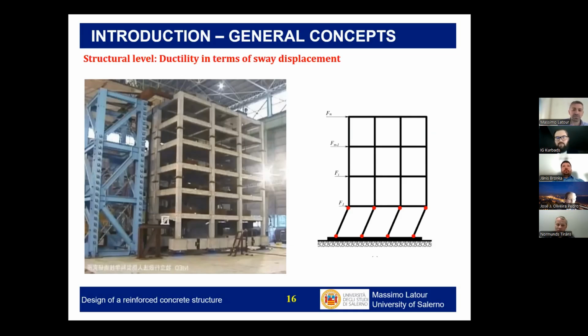But this is on the safe side because, as long as we increase the stiffness, placing the fixed foundation, and we neglect the damping of the piles in the soil, this will be for sure on the safe side. And this is the assumption that is typically made. But with this, I don't want to say that in a more advanced approach it's not possible to account for this damping. Years and years ago, I remember I had a design of a much bigger structure with a lot of piles, and it was considered the idea to evaluate the real stiffness of the piles, vertical and horizontal, and also the damping.